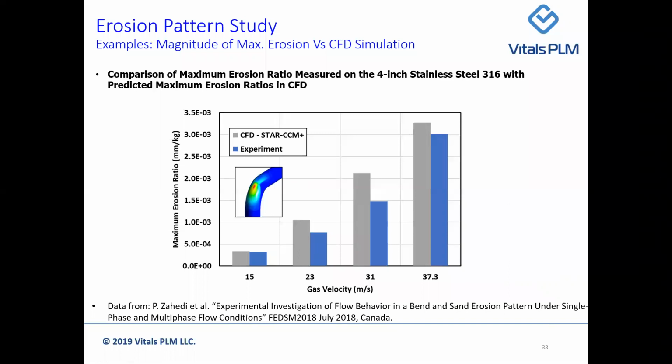There's another question. Any comments on steam erosion? I don't know if it means multi-phase flow conditions. Yeah, we can model coupled multi-phase flow simulations with erosion prediction models, so we can start running the simulation with multi-phase models like VOF or the Eulerian method, and then add a Lagrangian phase to the flow. So we'd be able to predict erosion in multi-phase flow conditions too.